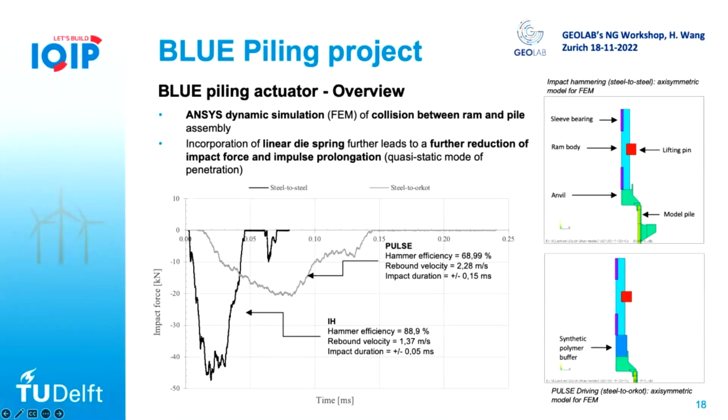And I think the following question is then, what happens if you go into clay? Yes, I think that will be the next topic. I guess we want to check, but in clay it really depends on what kind of clay in the offshore. If it's very soft clay, what we worry about more is pile running instead of really hammering the pile in. But if it's really stiff clay, then it may not be that efficient, but we need to look into that in the future, maybe.